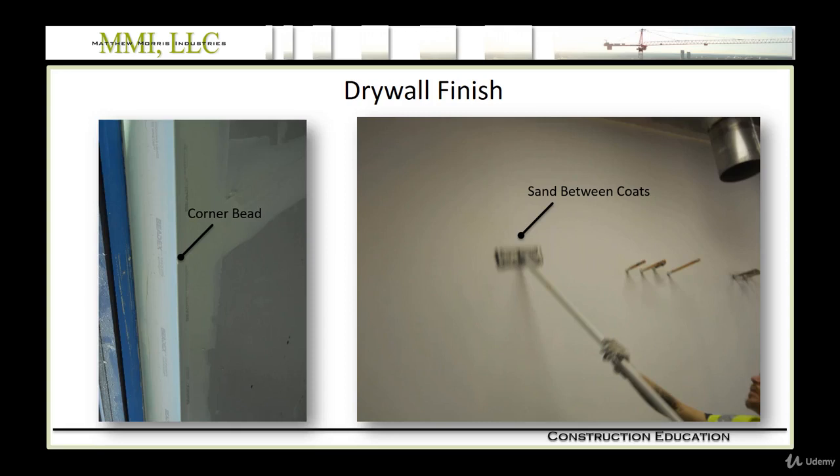Sometimes the schedule dictates that we go a little faster. So the drying process is important to prevent cracks, and so you can't just apply another layer without doing something different. And that something different is called hot mud, and that's quick setting joint compound to accelerate the curing process. And this allows for multiple coats in a single day. However, typically you don't use hot mud, and typically it takes 1 day per level of finish. So it's typically a solid week after you hang drywall before you have your finish complete.